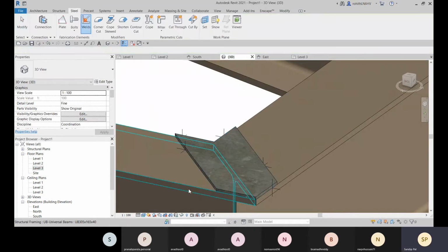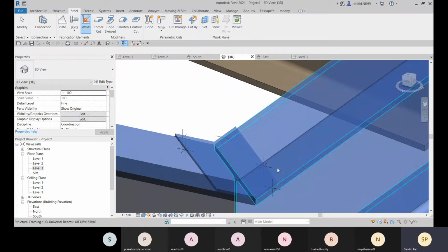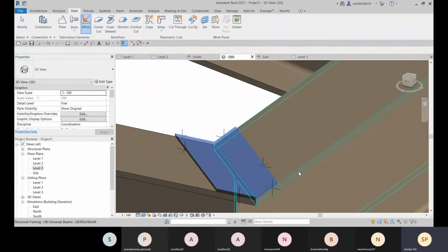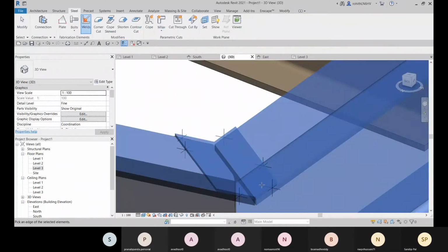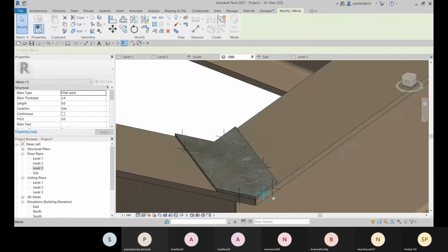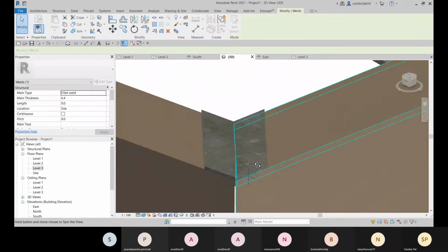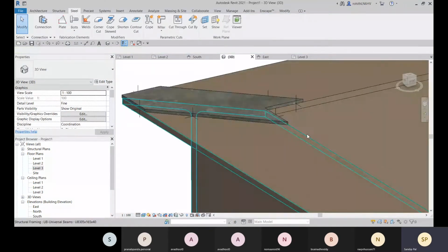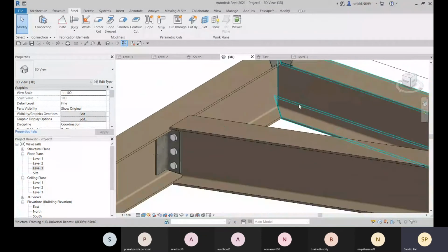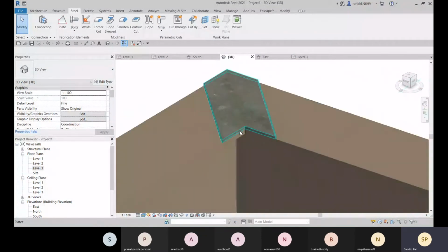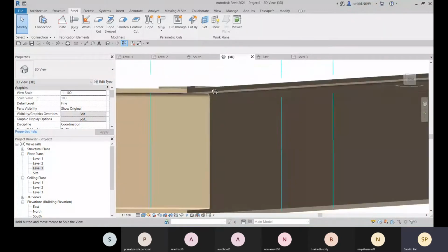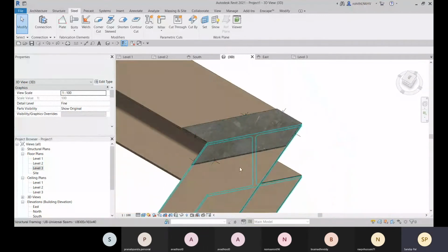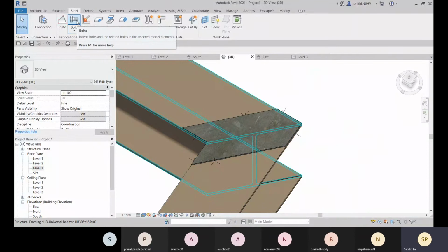WW, select this one, holding control, select the other two, press enter, and then specify the edges. Do the same. So if you already have applied, don't just apply again. Okay, so this way we will weld it. All right. And if you want to provide any bolt connection over there, you can also provide the bolt connections. For that, you can go for this bolt.